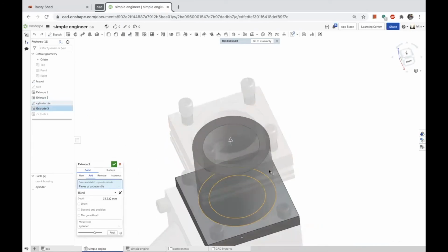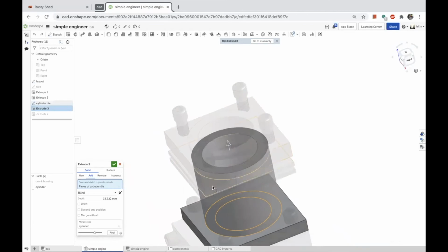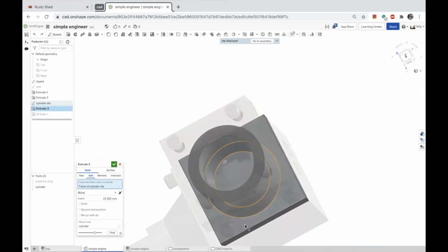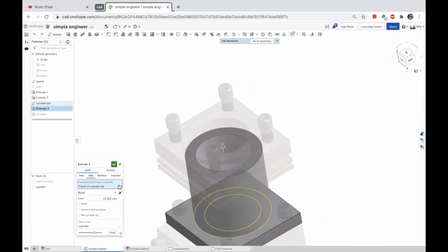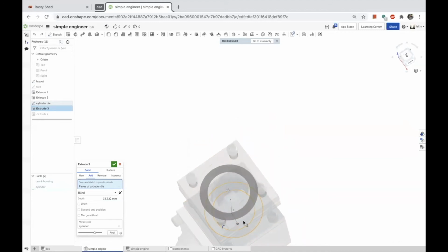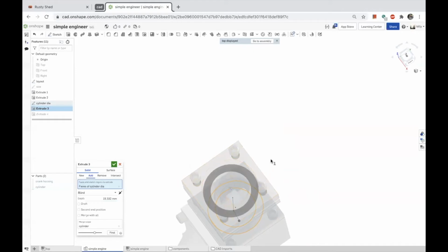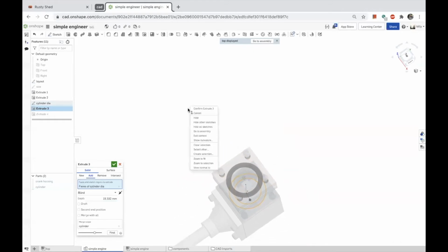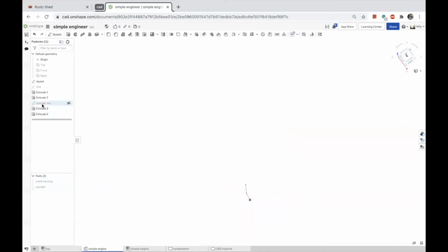So when I extruded this, I got the hole. And instead of doing it that way, on this sketch. Okay, in this case, it's having a problem figuring it out because I got that ghosted shape in here. You can always right mouse click and say exit the context.